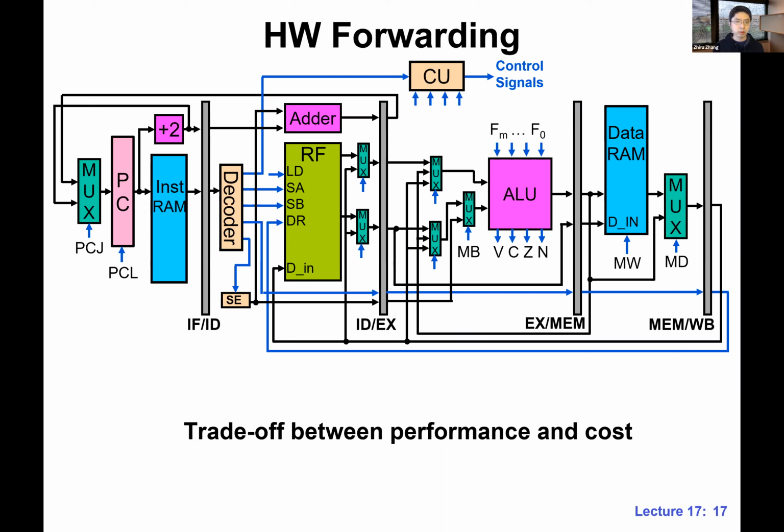We calculate the critical path for the entire pipeline. When we do the timing analysis, we need to do it between each pair of registers, and then we see what the final critical path is. That's how we determine the clock frequency. The good news is in most cases, these are fine. Of course, we will be paying some overhead, but really the benefit outweighs the overhead in this case, because we don't need to insert bubbles anymore. That is for this sequence of instructions.